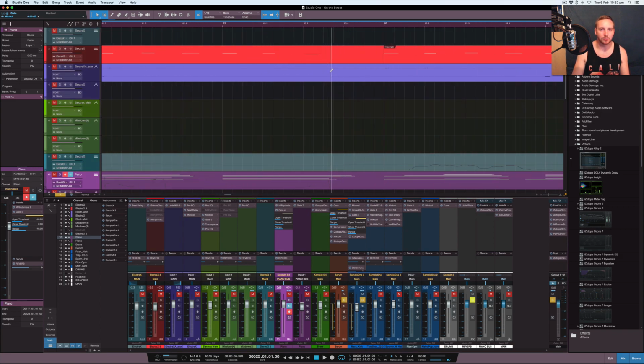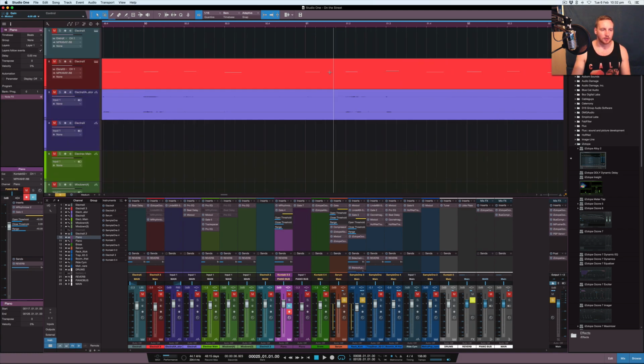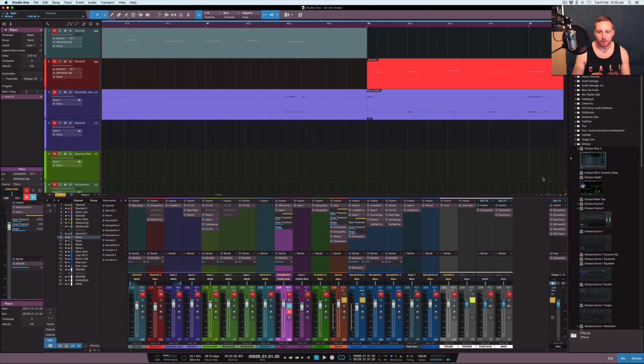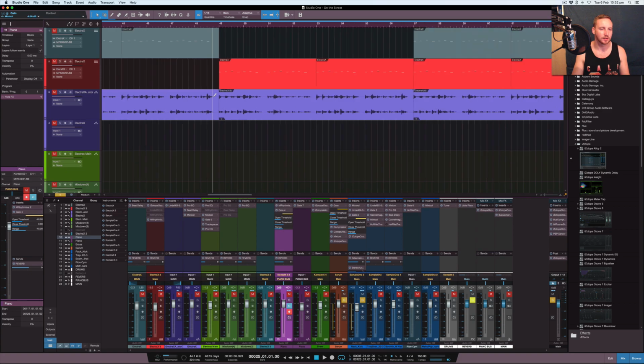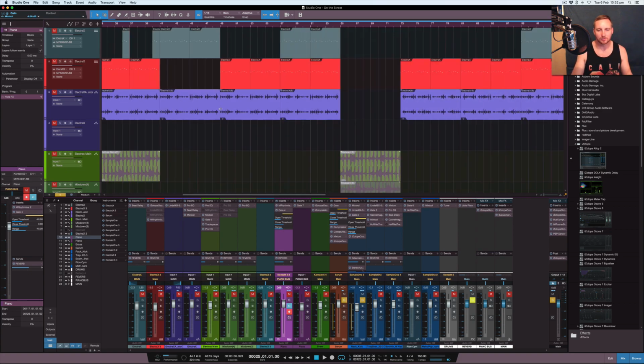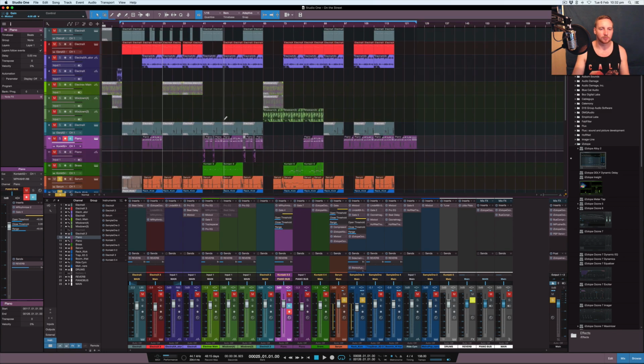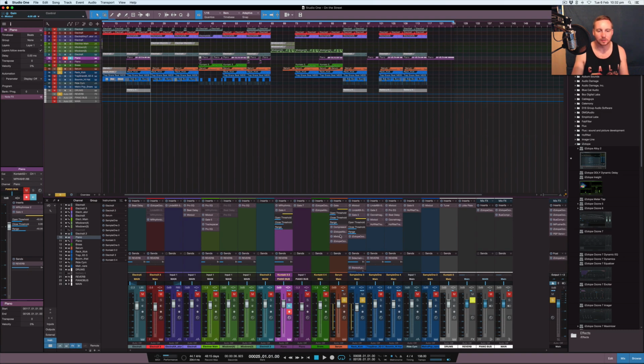If you can see here on the waveform, I'll just make it a little bit larger so you can see what's going on. The 0 dB line in the center there is what you have issues with if there's a DC offset or correction issue. It's basically a movement of the 0 dB line, which creates extra issues with headroom or even phase and stuff like that. So that's what this is preventing, if there is any. Usually I can hear issues when I hear it, so I put it on there.